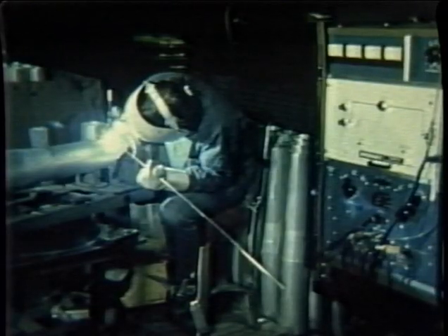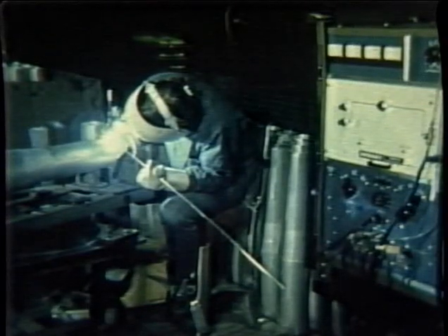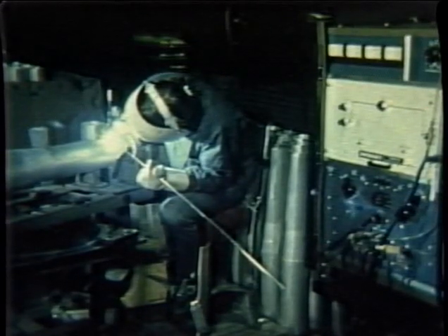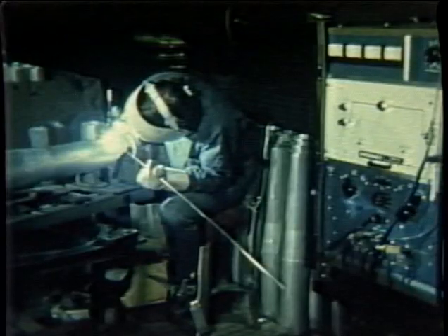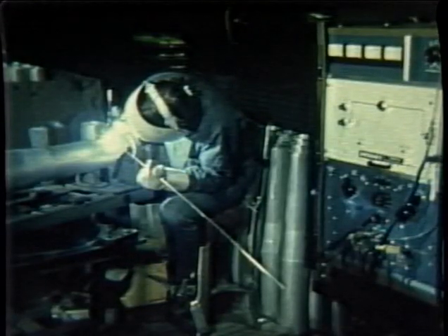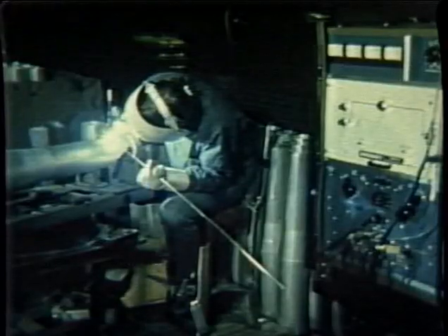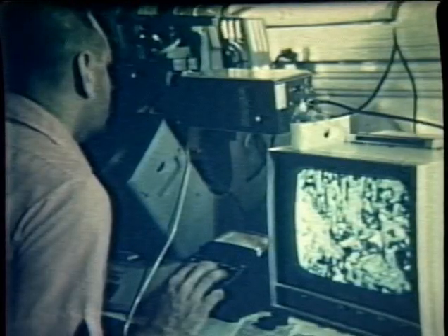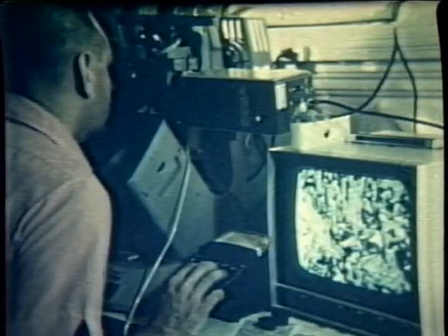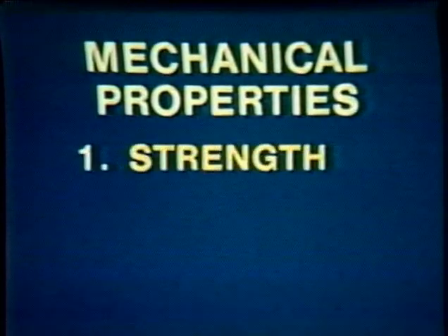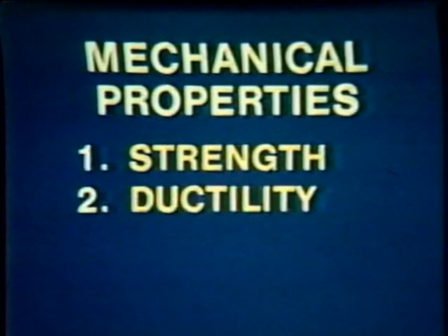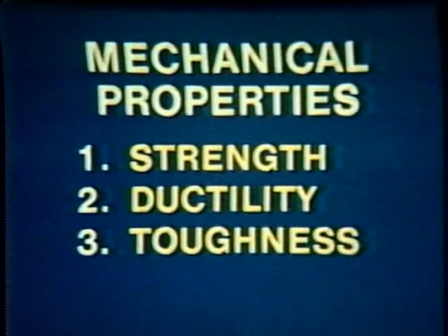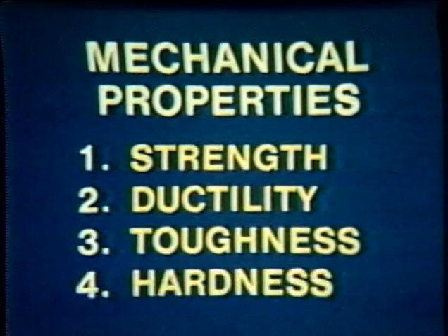Destructive testing can also be used to spot check the quality of production weldments by evaluating random selections of welded parts. This is commonly known as work sampling. Destructive testing has evolved into specialized methods which can determine the mechanical, chemical, and metallurgical properties of welded joints. The most important mechanical properties include strength, ductility, toughness, and hardness.